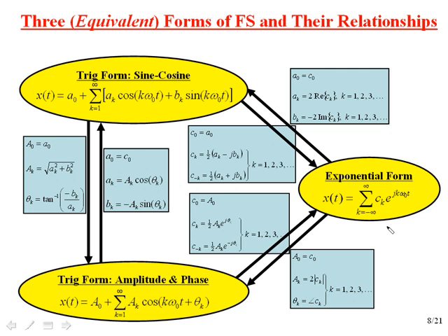Let's go from the complex exponential form to another form of trig form, which is sine cosine. So here we have A0 out in front for our DC offset. We're still summing over just the positive integers, just like in this trig form. But here we have two terms. Each term of the sum consists of two individual terms. One is a cosine term, one is a sine term.